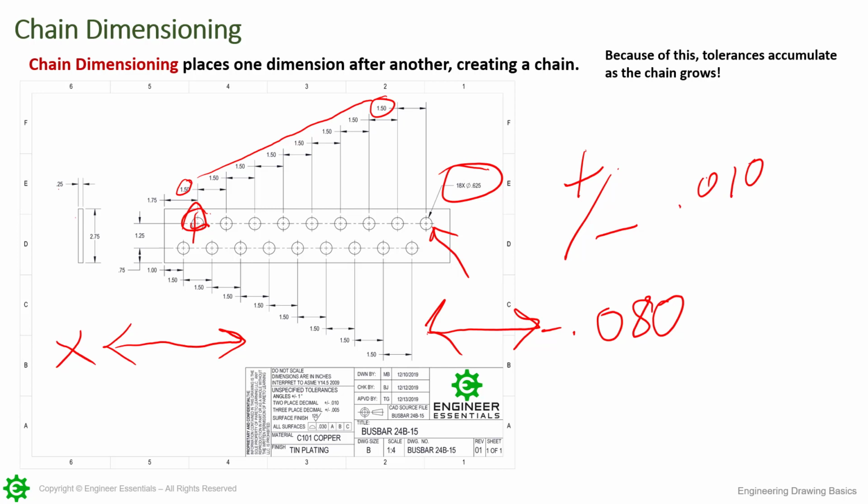Or we could go back in, as far as design goes, and we could start making slots instead of holes. We could do slots either on this part or the mating component, so that no matter what, we're not going to put in all of the slot up and down in Y. We could leave the slot width at the 625, but we would extend this out 80 thousandths both directions and create slot features in there, so that as this tolerance accumulates, if we're going to do it this way, coming from the rail, then we would always be able to clear the bolt.